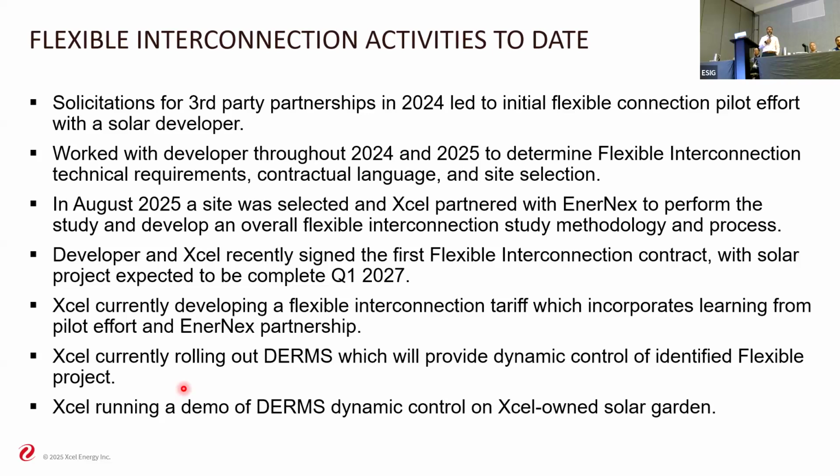There's obviously a little bit of uncertainty and still a debated topic in the industry around levels of curtailment. As you add more systems and more flexible interconnection arrangements, depending on principles of access, whether you do a last in, first off, or pro rata curtailment, that may all change over time. But this developer, at the curtailment levels that we studied, felt confident enough to move forward without missing their hurdle rate for their project.